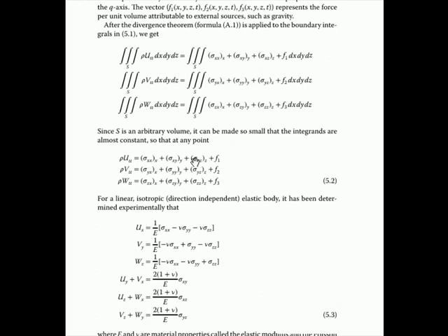Now, how do these stresses relate to the displacements? Well, they are related by the following formulas, which we aren't going to derive, but it's known that the stresses are related to the displacements by these equations here, where E is the elastic modulus, Young's modulus, and nu is the Poisson ratio.